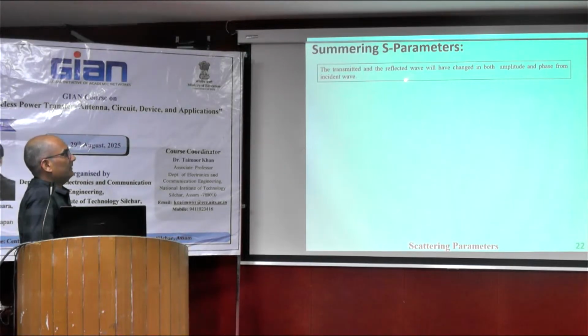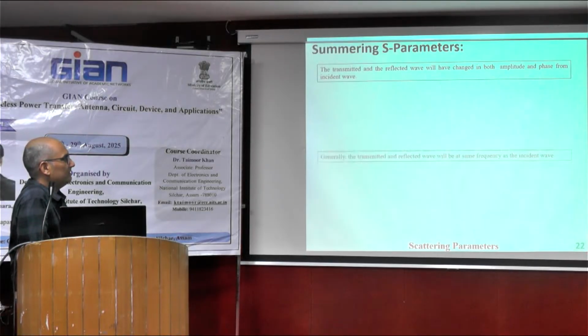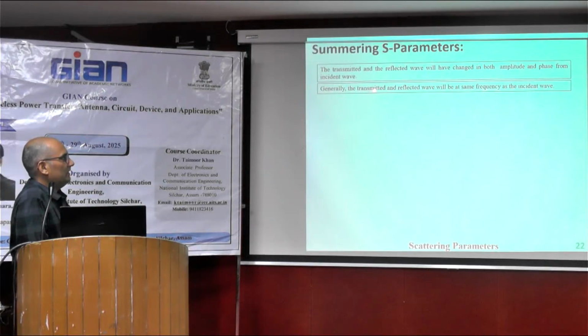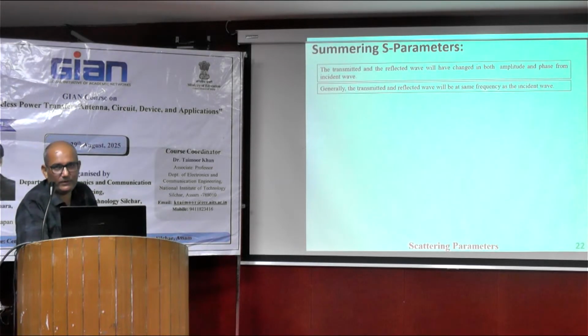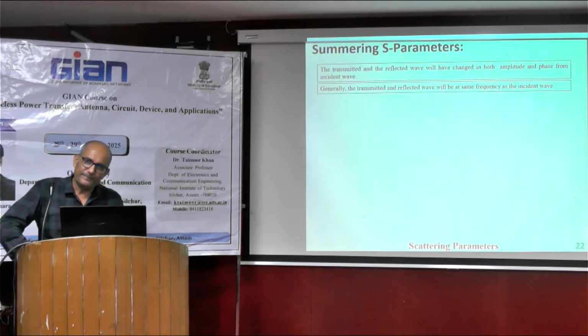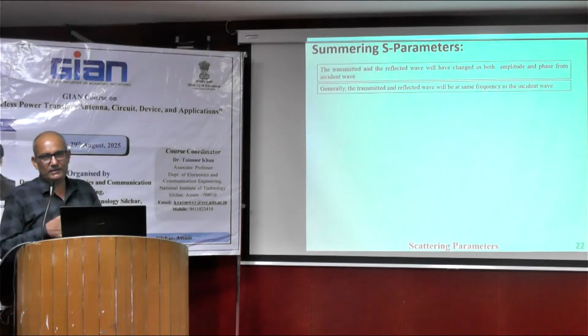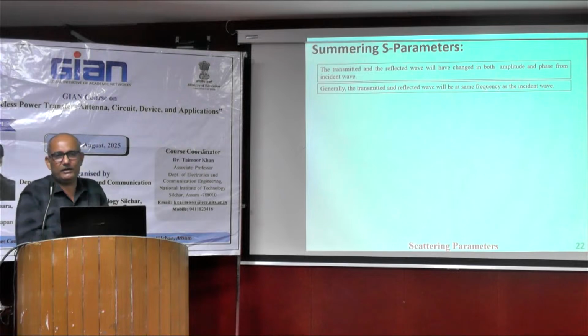Summary of this experiment: the transmitted and the reflected wave will have changed in both amplitude and phase from the incident wave. That is absolutely correct. Generally, the transmitted and reflected wave will be at the same frequency as the incident wave. Frequency will not be changed. Frequency will change only if there is something like a Doppler shift happening.